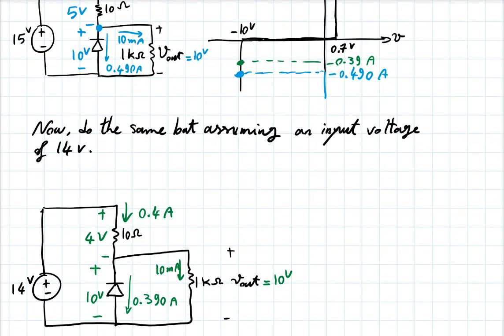So if you had built a rectifier and a filter that gave you an output that had the ripple, swinging between 14 and 15 volts, and then you put this circuit after that output, then you would regulate it to 10 volts.